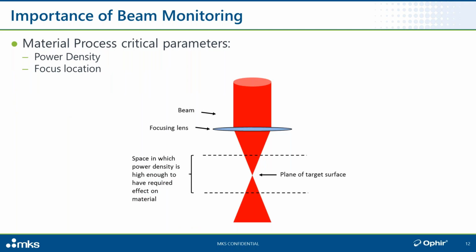Here's a schematic drawing, pardon my artistic skills or lack thereof, of a typical materials processing application, a very generic one. You have a beam, you have some kind of focusing optics, and then the beam gets focused, and if nothing stops it along the way, it'll continue past focus and defocus. In order to melt, vaporize, or otherwise zap the given material, we want a beam with a given power and of course a given wavelength to be focused down to a given diameter such that the power density is high enough to do the work.